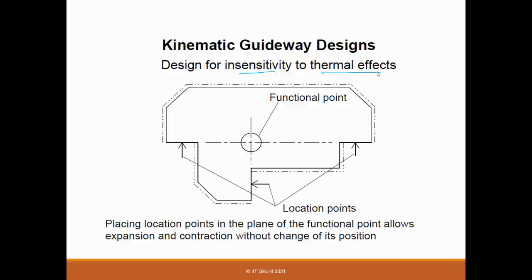Secondly, if thermal things are happening, thermal strain is developed and some deformations are happening, then you try to find locations which are insensitive to them, right? That's why sometimes we talk about design for insensitivity. Those points will not move even if there is any thermal deformation on the part. So in this case,